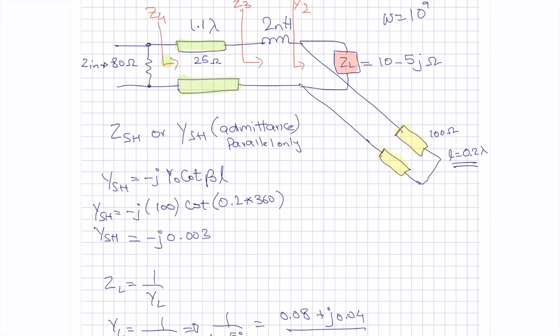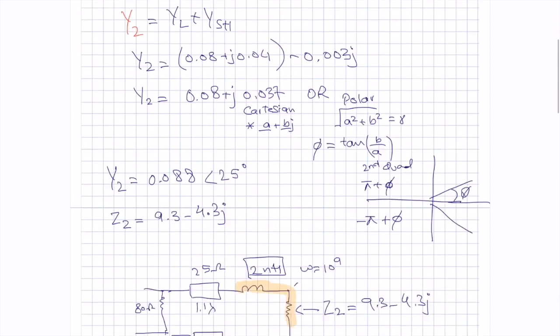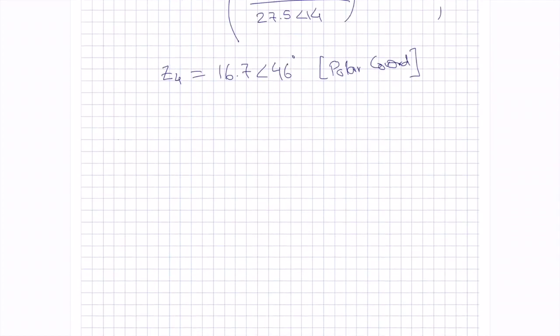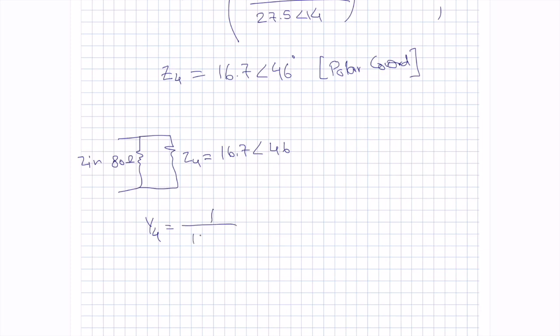Now we have to work with admittance, since the total circuit at this point in time will look like this. It's just two elements together. The one that was already given to us, 80, and this Z4 that we did here, which is actually given to us in polar coordinates. So if I have to add these two things together, I need to use admittance. So admittance is basically Y4. I can use that Y4, and Y4 is just an inverse of this.